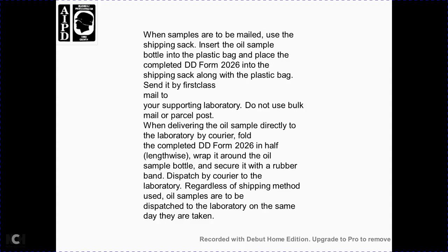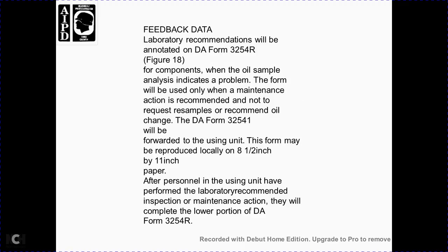Fold the completed DD Form 2026 in half lengthwise, wrap it around the oil sample bottle, and secure it with a rubber band. Dispatch to the laboratory regardless of the shipping method used. Oil samples should be dispatched to the laboratory on the same day as they are taken.